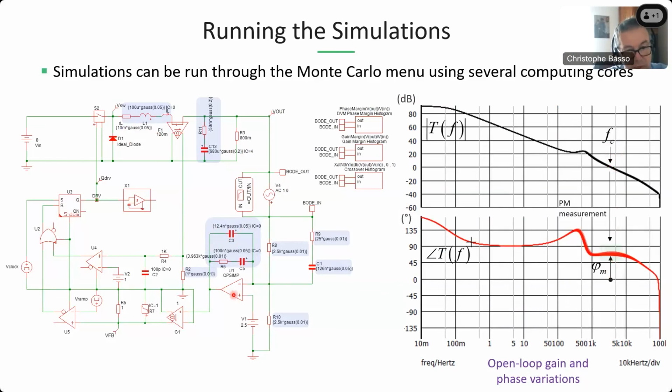Of course, I could here add other characteristics of the op-amp, like the low frequency pole and the open loop gain. If you look at the datasheet of some op-amps, the open loop gain minimum value can go fairly low. If you push crossover and have a quite high burden on this guy here, it's important to make sure that the AC response of the op-amp is not that much affected by the open loop gain that has dropped to, between brackets, quite a low value for some samples.